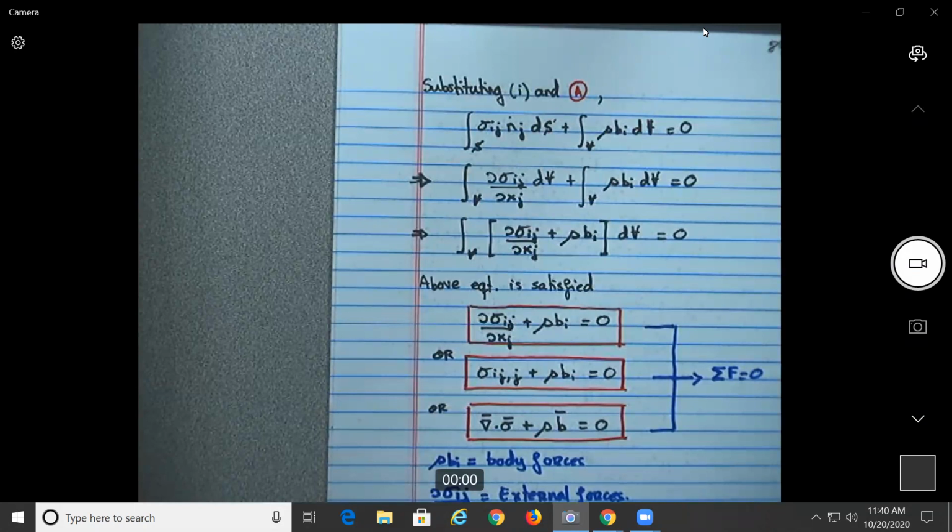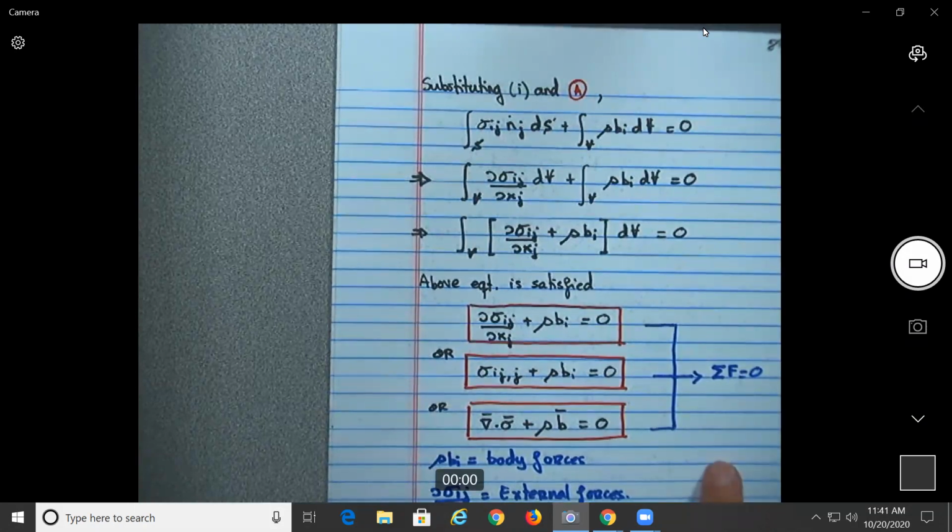So what do you do every single time you need to derive the equation of something internal? What do you do every single time in engineering? How do you make those internal forces become external so that you can use Newton's equation? You break the solid, you make a cut, no? So by making a cut, you expose internal forces, they become external. Now you can apply Newton's equations.